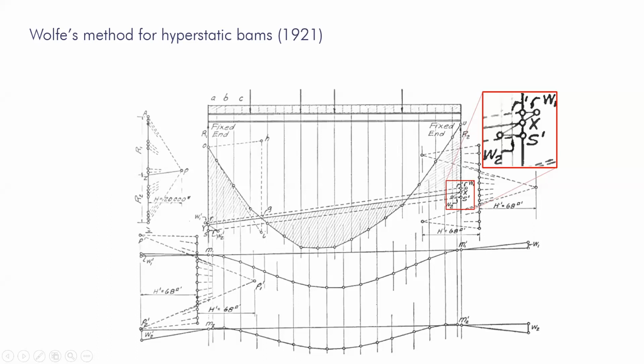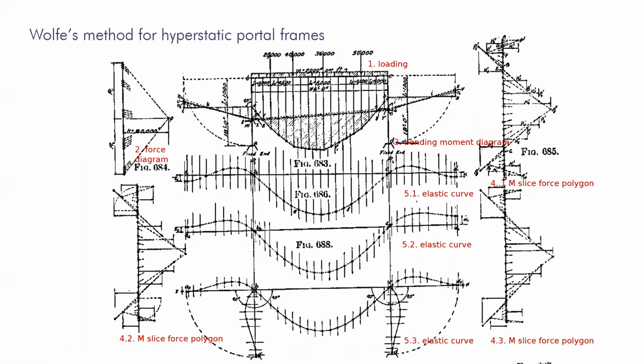Wolfe applied it also on portal frames, so you can see that you can describe the system of portal frames with two side spans as a simple continuous beam. You are just making the support column rotate to become horizontal, and the sum of bending force that will be met in the column and in the side span will be presented as the side span of a hyperstatic structure. So you see the same procedure with the two deviations, the integration that will be made to solve and get the result, then balancing the force according to the respective stiffness between the side span and the column span.